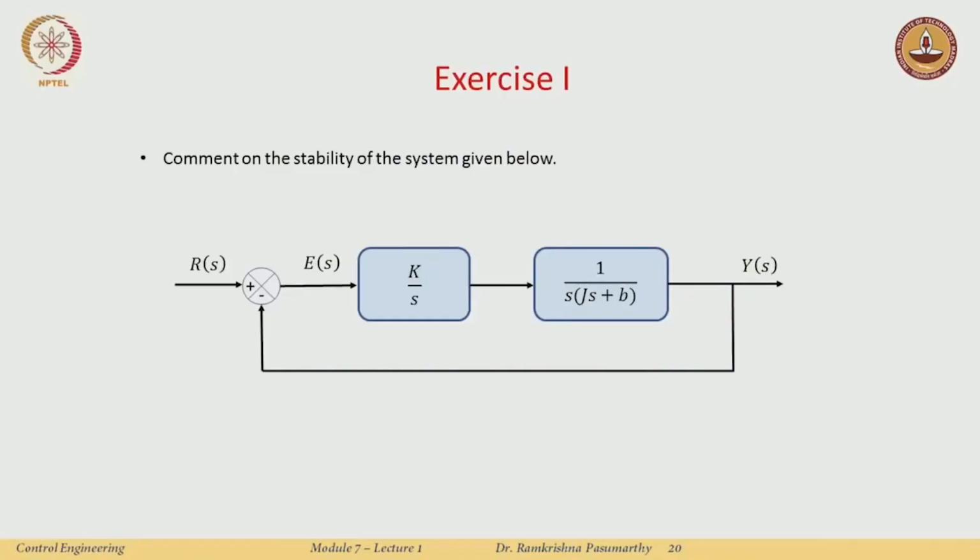First, proportional control improves my transient response and also helps in reducing the steady state error, but does not eliminate it completely. Second, with integral action, I add an integrator to the system, which means I add a pole at the origin, and it helps in reducing the steady state error to 0 in this particular case, which is now a type 1 system. For higher order systems, it may not always be desirable to keep buying integrators and dumping them into the system. It may not work, and we will see why.